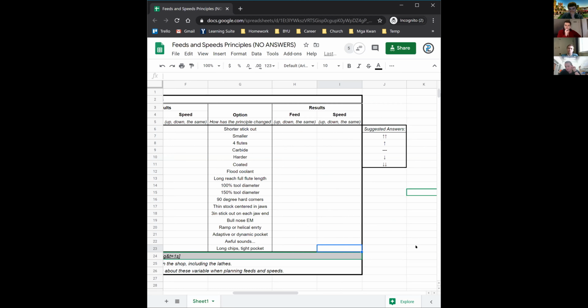Yeah, and another thing to watch out for is when you say speed, you can either be talking about spindle speed or surface feet per minute. As a general rule, I tend to prefer talking about things in terms of chip load and surface feet rather than flute life. The tool's life depends a little more on just how you're using it, if the flutes are wearing out or not. Although it's way easier to break the one without the solid core going up.